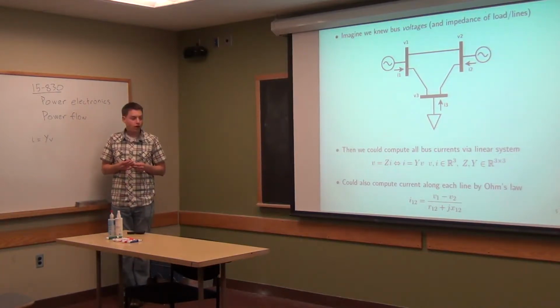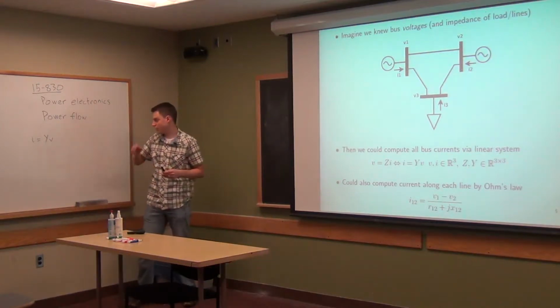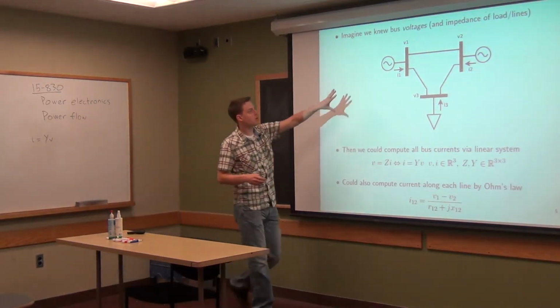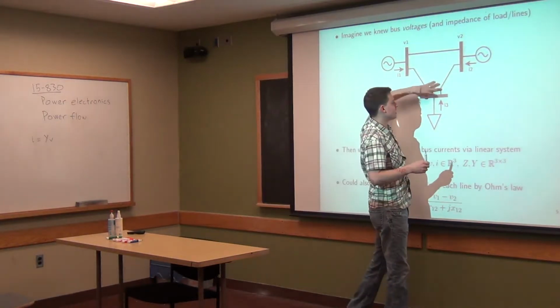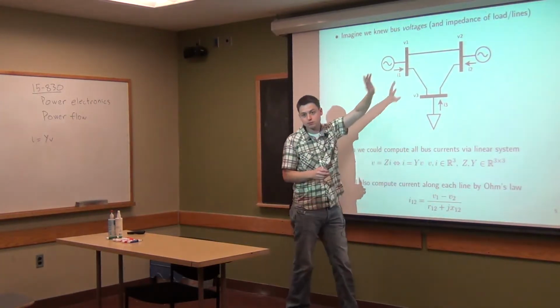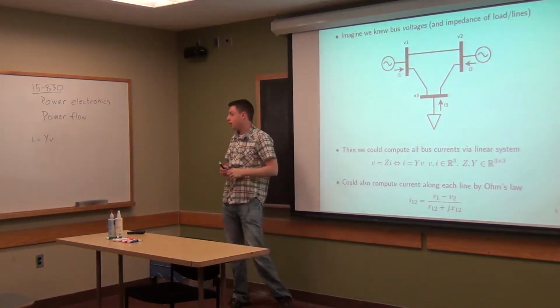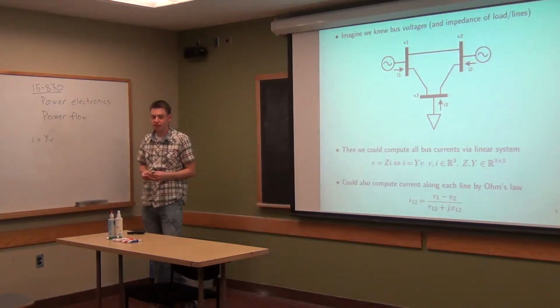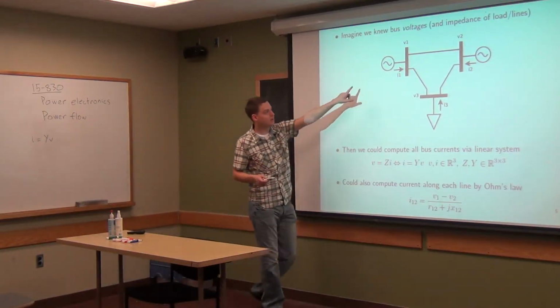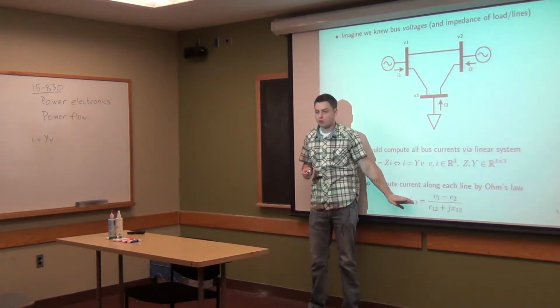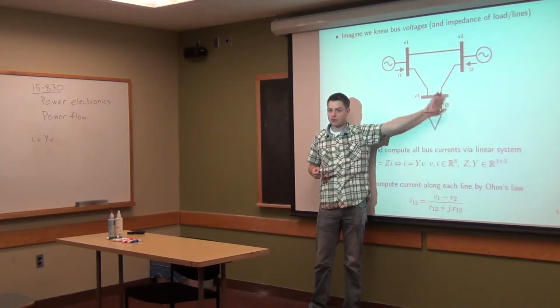So that's fine. And in fact, that's answering one question, right? That's answering the question of what are the voltages and currents at all these buses. That's a good thing to know. But then if we want to actually know how much current is flowing through any line, well, then we can just apply Ohm's law and figure out what the actual current here is.